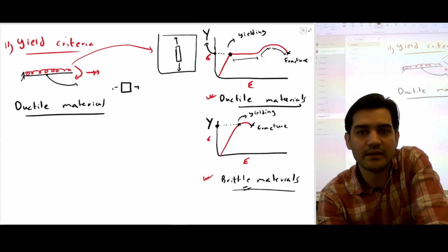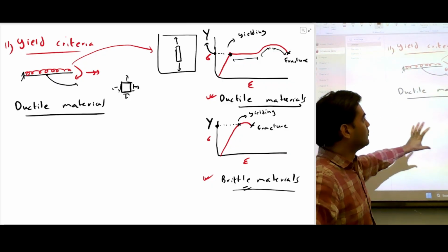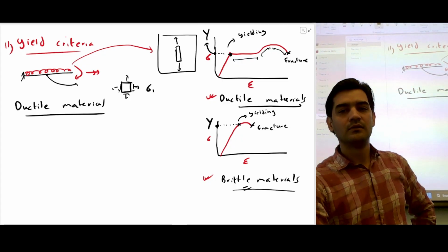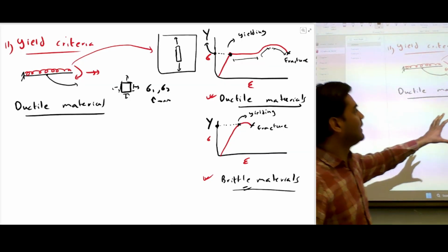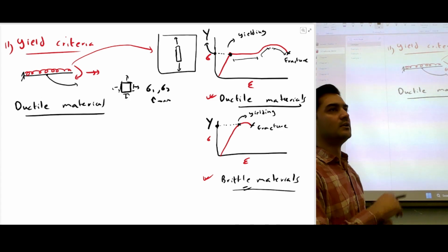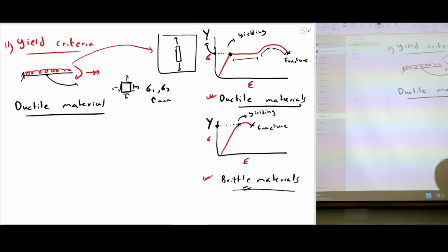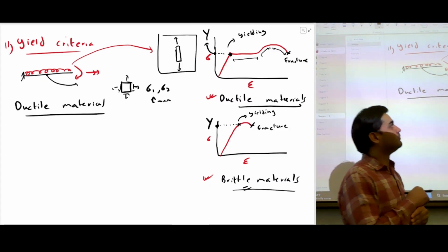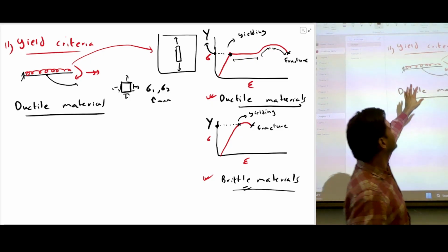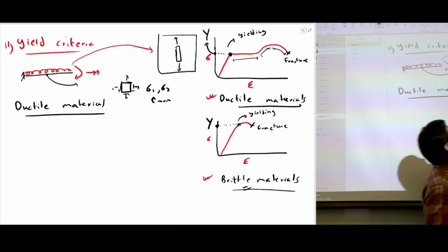We can take the stress element out. We know the stress element has different loads, and then we're going to perform everything we were doing in Mohr circle, and we'll calculate stress 1, stress 2, and tau max. We can calculate these stresses using Mohr circle, using transformation equations, using equations for the maximum principal stresses. These are the maximum stresses which we will get. We will not get more stresses than this. In a given loading condition, we can extract the stress element and calculate the maximum stresses we will observe.